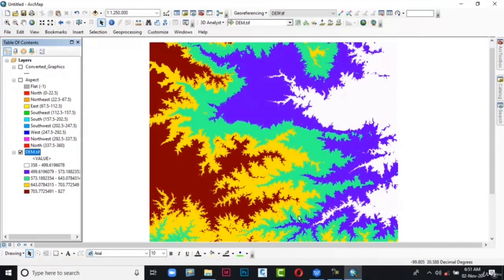The dialog box is closed and the color has been applied here, as you can see. And here you go, these are the digital elevation model legends in the table of content. That is primarily about the analysis and assessing of digital elevation model for further use. You can definitely explore more options in 3D Analyst or Spatial Analyst, etc.